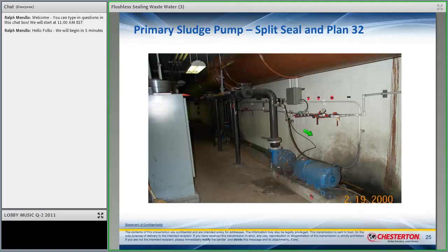You're trying to remove the water, right? It's all about separation, because you're reacting to biologicals to break down the sludge, and then really what you want to do is separate the solids that cannot be broken down from the biologicals. The biologicals can be handled with the water, and those solids eventually go to landfill, become fertilizer, whatever you want to do with that, right?